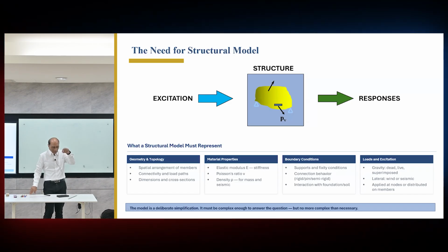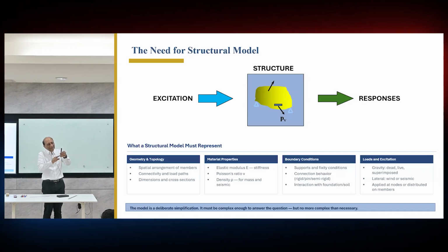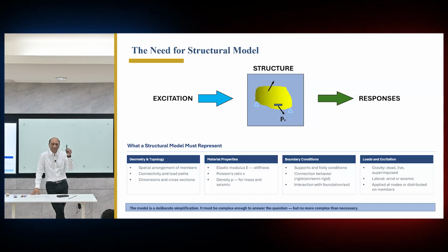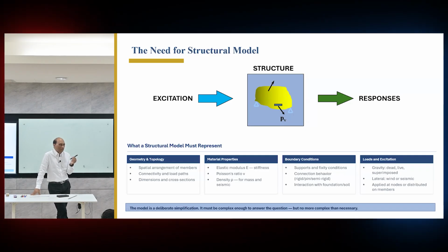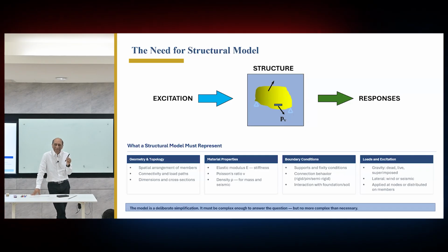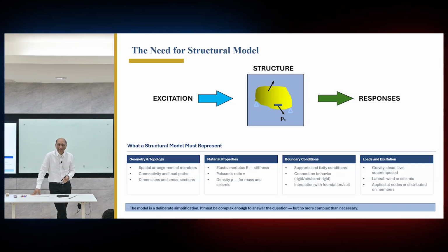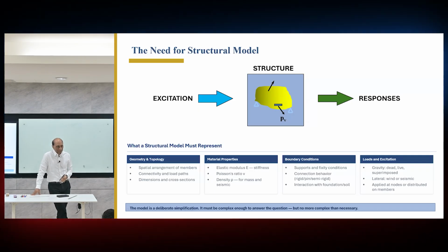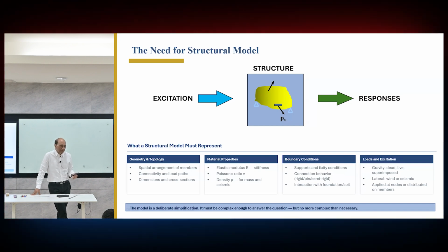They just stop the building column, like this one, and here they put a line, and then this is my pin support. So they completely eliminate the boundary from the model and represent it in the simplest, most inaccurate manner. So boundary modeling is often the worst of all the errors that we make, because we never model the boundary as it should be modeled.